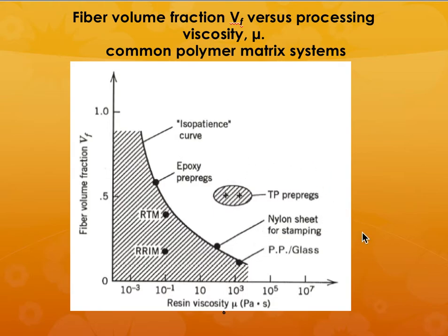But if you have a thermoplastic prepreg, you may have a solidification happening. The matrix resin will become liquid and it will start flowing nicely, and then you shut down the furnace so that it starts solidifying and becoming completely solid.